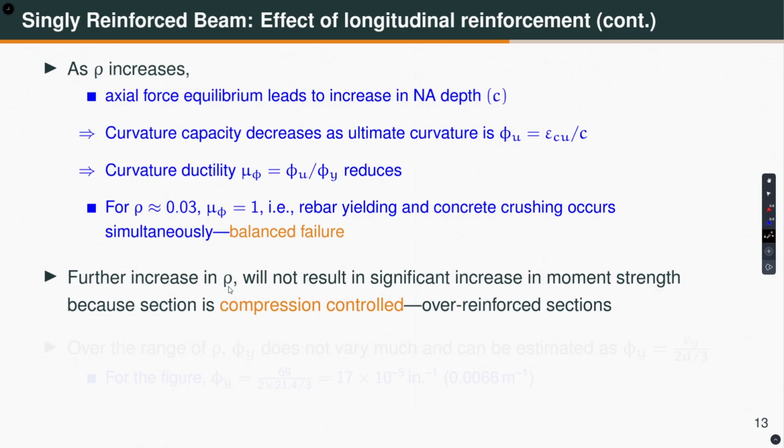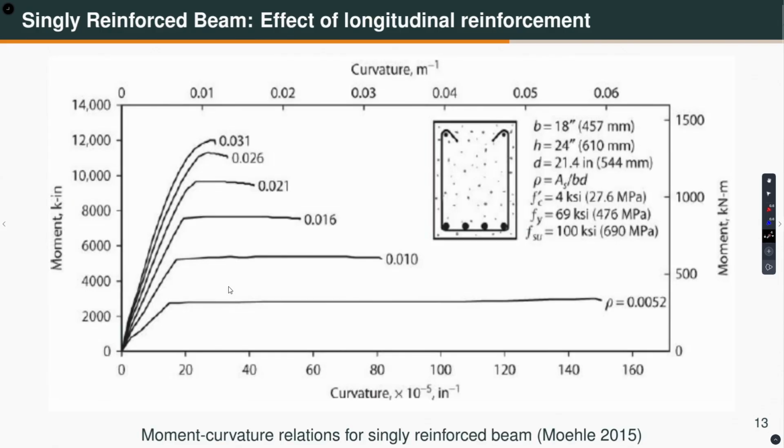In fact, IS 456-2000 puts a limit on the neutral axis depth, so that you can never design an over reinforced cross section. Another important thing that I want you to notice here: what is this called? The curvature, the yield curvature. This is the yield curvature.